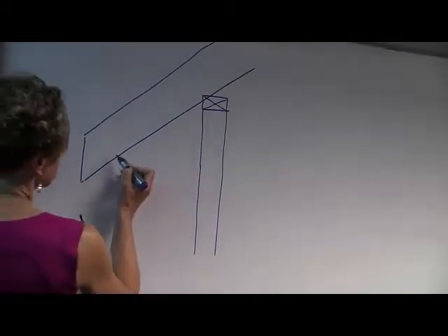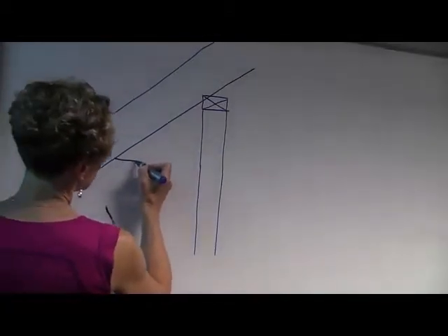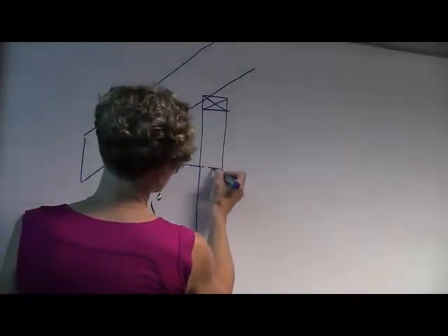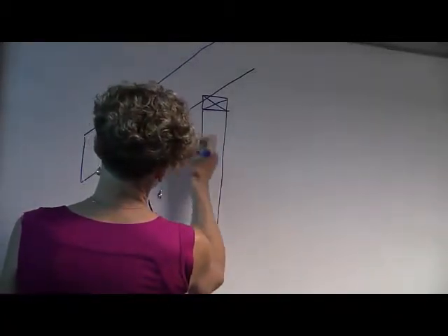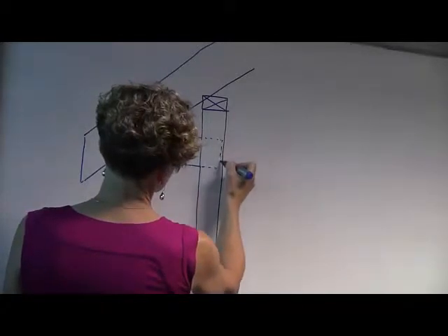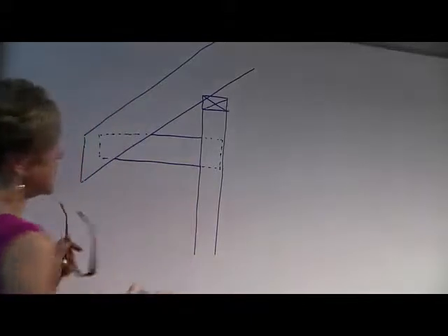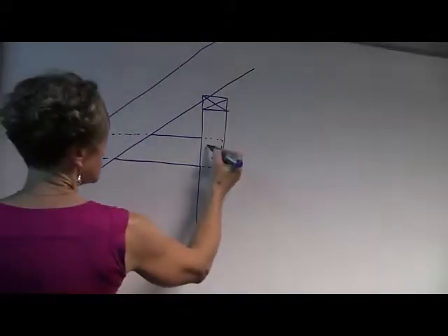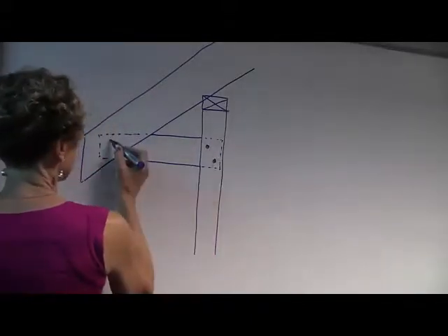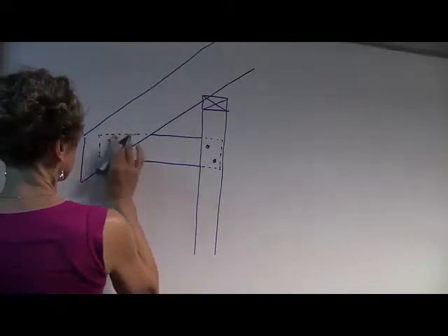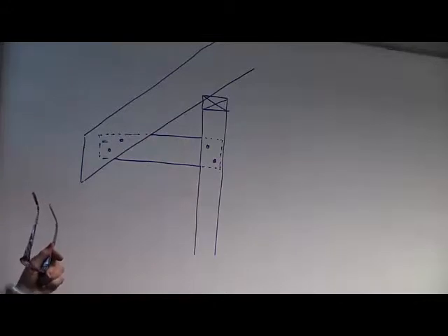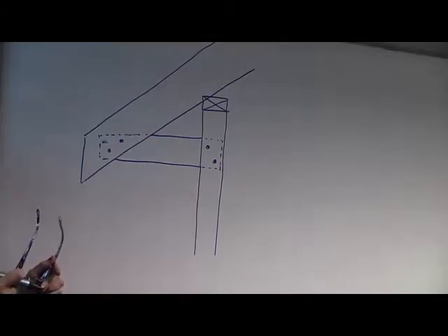So sometimes there's a timber member something like that, which is bolted back into the wall frame, and that stabilises the end of your overhang and provides additional support.